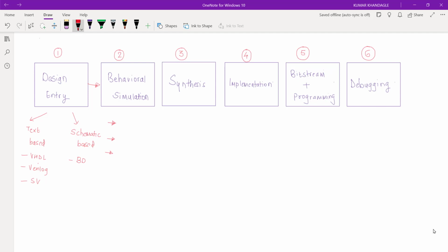Common optimization strategies include the number of BUFGs that you could invoke in a design. The second one that we frequently utilize is the encoding style, when we have a complex FSM. The third one could be whether you want to control the dynamic power dissipation, so adding clock gating. These are the 3 popular techniques that we frequently utilize in synthesis.